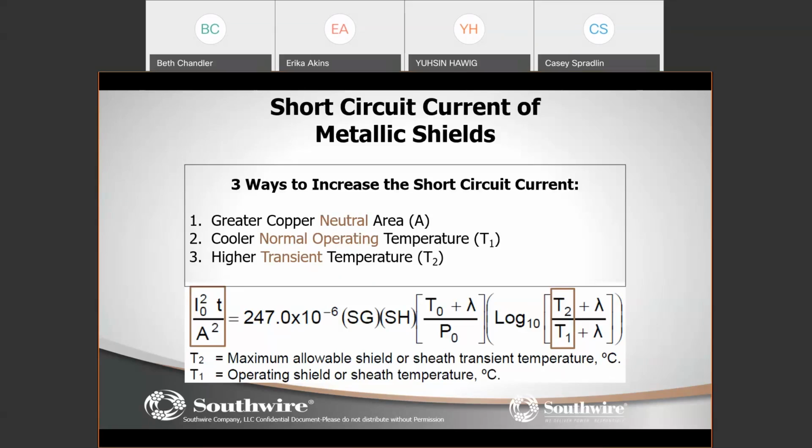That comes along with the thermoset or cross-linked jacket, in that it allows you to operate the short circuit current at a higher temperature. So that allows you to operate the neutrals at a higher temperature. Therefore, it provides additional short circuit current. Well, if there's only so much needed, you can actually take advantage of that and reduce.